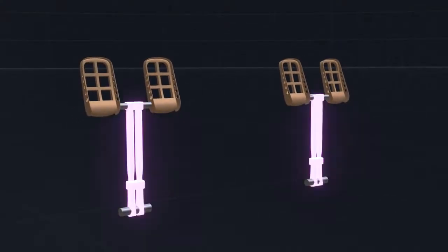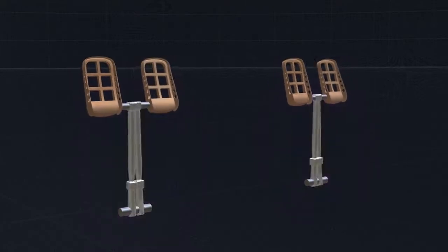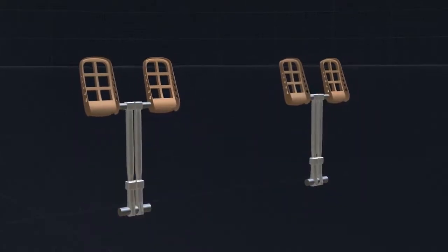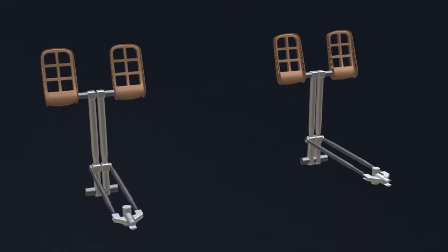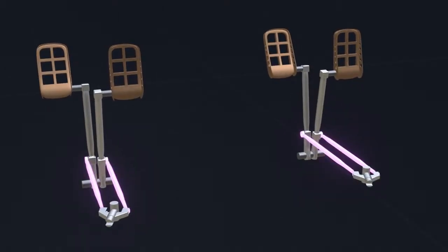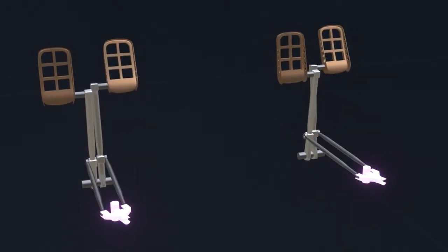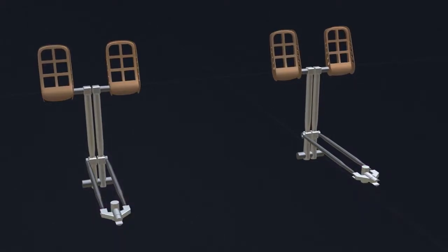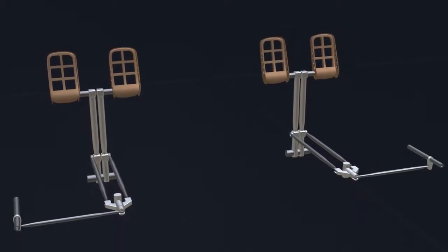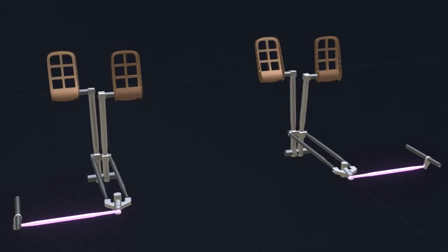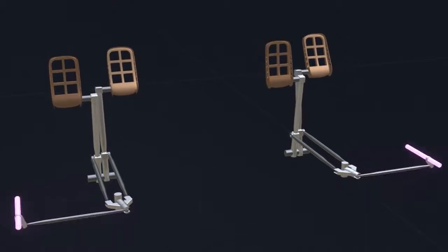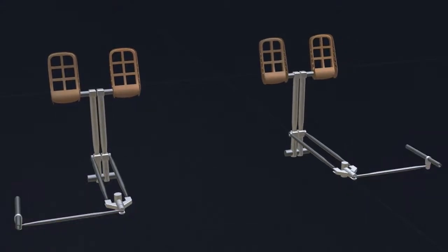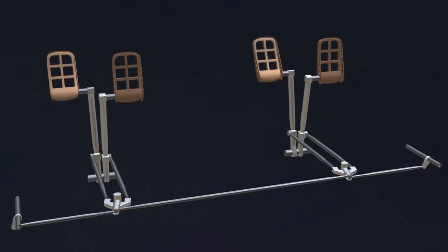The pedals move on their pivot axis, with the help of pedal arms. Control rods connected to the arms rotate the jackshaft assembly. The jackshafts move the control rods, connected to the left and right shaft assembly. The rods move to rotate the shaft assemblies. The 2 sets of pedals are connected with a bus rod. The bus rod ensures when one pilot operates the pedals, the other side has the same movement. This gives the other pilot an indication of pedal position.